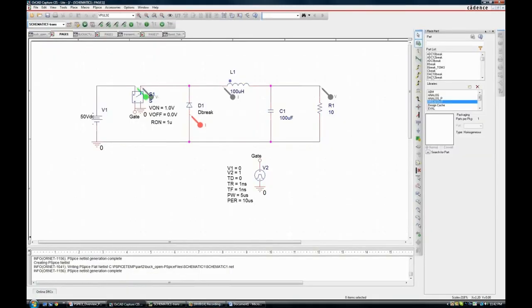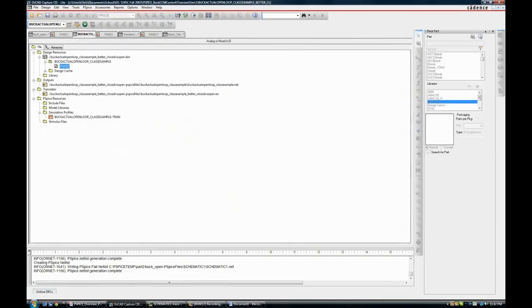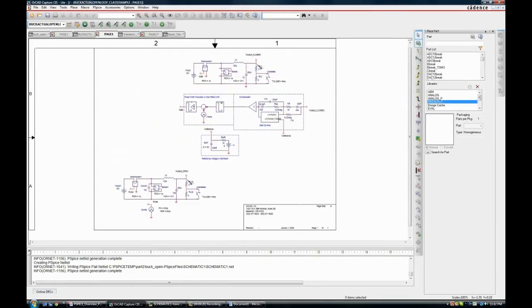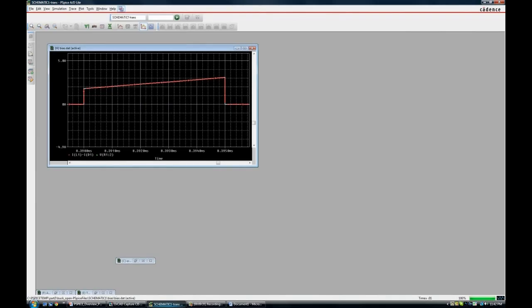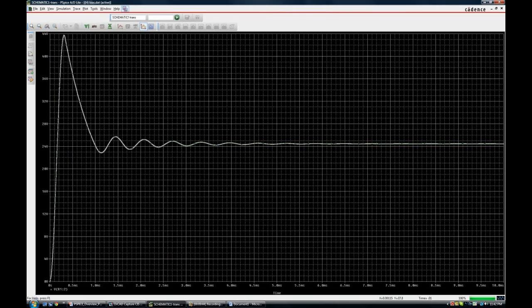Now let's change gears to another simulation. This kind of focuses on the closed loop example. If you recall, if we go back to the example that we just had and we look at strictly the output voltage, I'll take all these markers off, I'll look at the output voltage here, I'll right click, say End Mode, and I'll go full screen, zoom fit. There is our data, our output voltage. It overshoots tremendously. And of course it does settle in on the desired operating point at 24 volts after a lot of ring, milliseconds and milliseconds of ring.